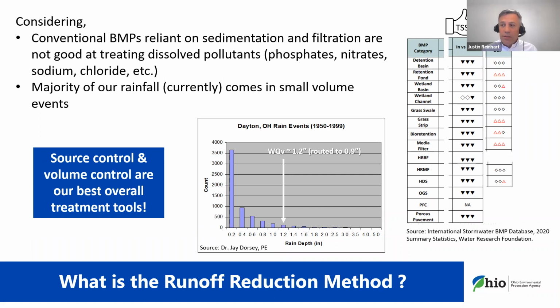Well, let's also take into consideration small storm hydrology, or the concept that the vast majority of our total volume of rainfall and runoff is produced in small events that happen dispersed across the year. If we add this up on a cumulative basis over the course of a year or any period of time, we can actually capture a lot of stormwater by capturing small events. And that whole model is built into the way we approach water quality, and most folks do.